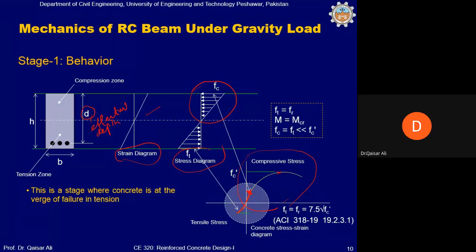And if you remember, in one of our previous slides, we discussed the modulus of rupture, or flexure tensile strength of the beam, for a beam subjected to a point load like this. We said that the flexure tensile strength of the beam can be calculated from the flexure stress formula: f_r is equal to 6M divided by bh squared.